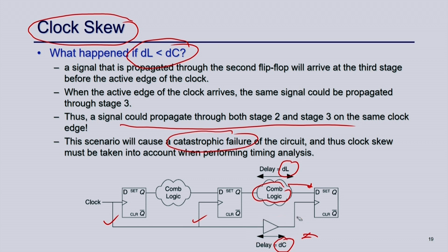Suppose I am talking about clock 2. Usually in clock 2, whatever the data is here will come here, and whatever the data of this register will go out. In clock 3, whatever the data of this comes out here, and the data fed in clock 2 will come out of this register now.